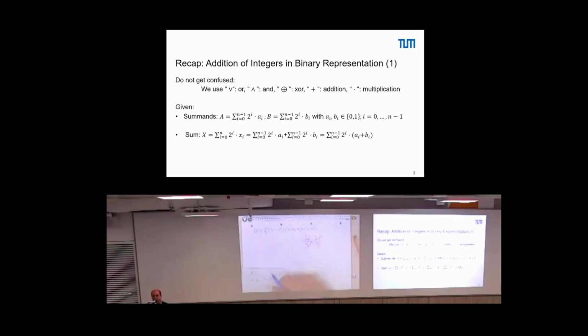And now if we want to continue this, well, we just put another full adder here, and this full adder here takes A2, B2, generates then S2 and C2, which effectively, this term here corresponds to that full adder.